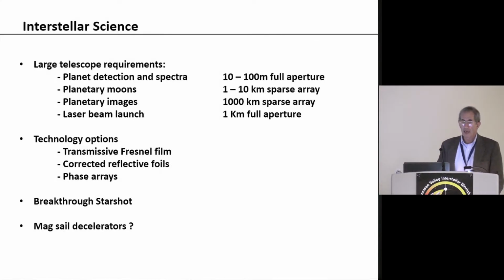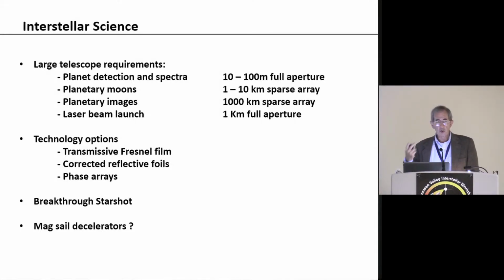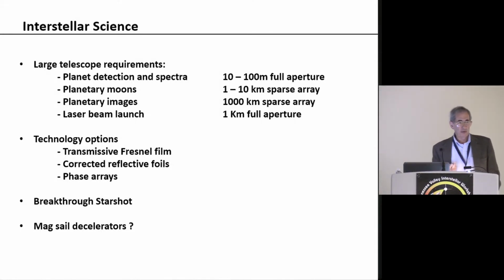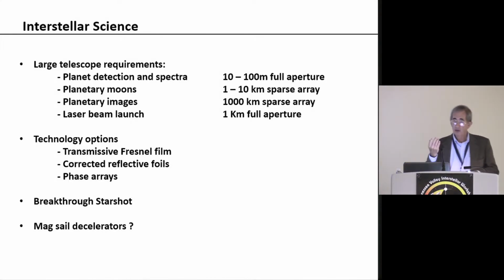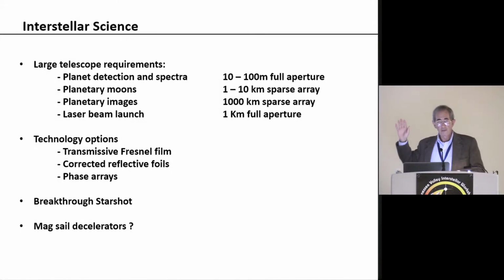Out at the Livermore Labs, we built a 5-meter demonstration of that out of a thin glass, and you can go up to much greater sizes. These are very slow lenses. F numbers are like 100. But in the floppy dimension of your optic, your tolerances go like the F number squared. So you can actually have tolerances of millimeters up to a centimeter in that, which is a lot easier to do.